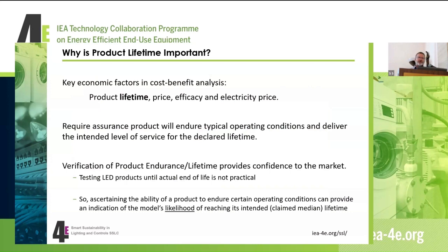Okay, so why is product lifetime important? This is something we probably need to establish to start with. Why do we need to worry about it? Well, it's a key economic factor in terms of our cost-benefit analysis of the utilising of a product. Along with the lifetime, we need to know about the product price, the product's energy efficiency, known as its efficacy, and we also need electricity price. Those four elements are utilised to determine the return of the benefit that we get from the cost of buying a more efficient product and the less electricity we use.